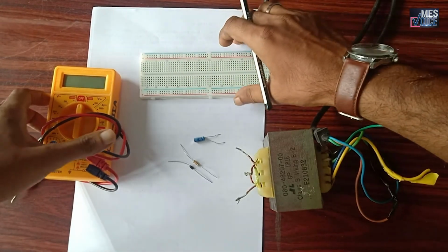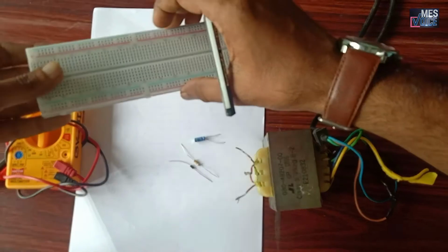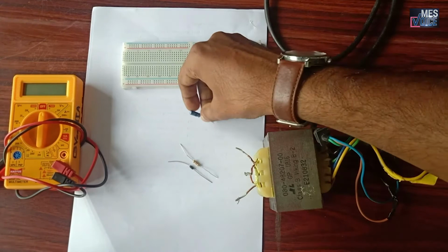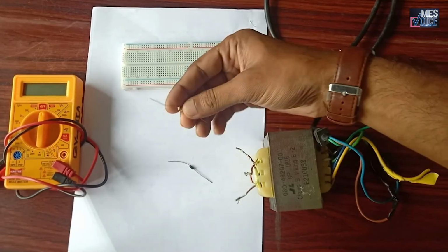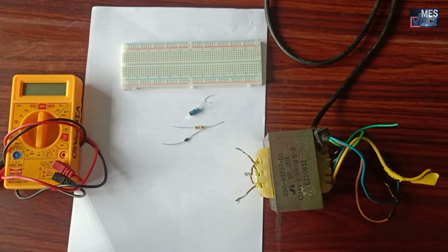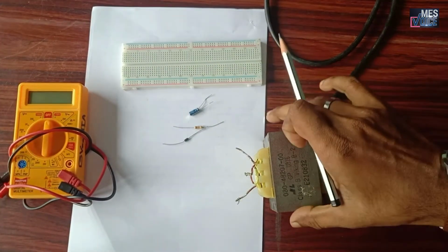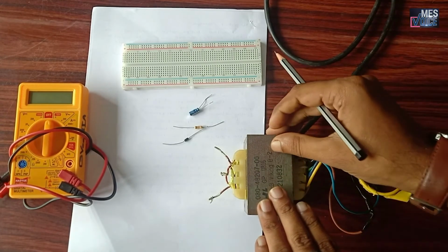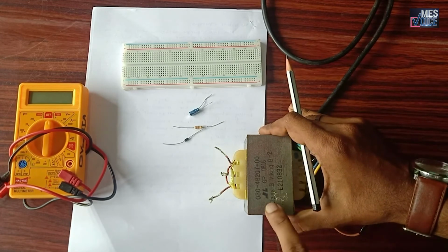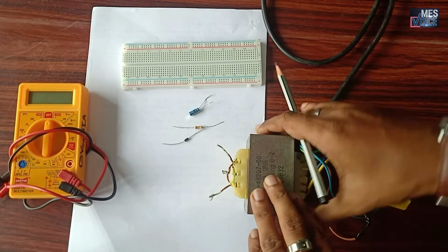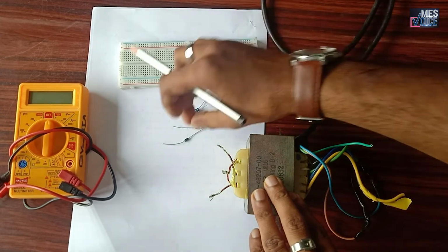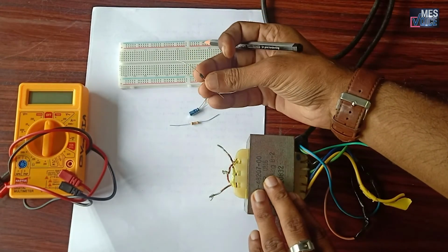So here we have to connect the circuit of the half-wave rectifier on the breadboard. I am adding a filter capacitor of 100 μF, and we have a resistor of 1 kilo ohm and the diode 1N4007. If you want, then we can use a multimeter as always. And this is the transformer. Here I am taking 15 volt peak to peak voltage at the output, I mean the secondary of the transformer, right? So we're going to make the circuit diagram on the breadboard.